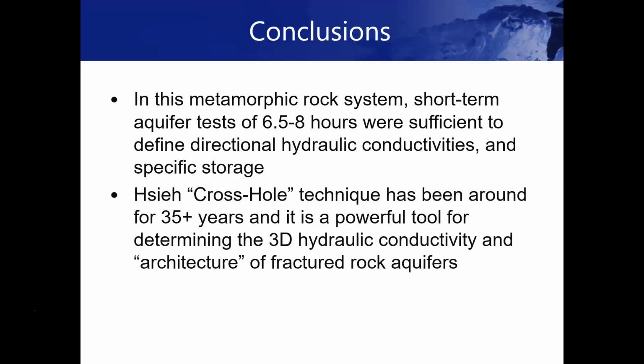So I think what we found here is that short-term aquifer tests of really anywhere between 6.5 and 8 hours were more than sufficient to define the hydraulic conductivities of this rock and the specific storage. We think of aquifer tests as being 24 hours, 72 hours if you're doing a water supply well or something that's mandated in New York State. But when you're doing this kind of fractured rock testing, I don't think you need to be wed to that.